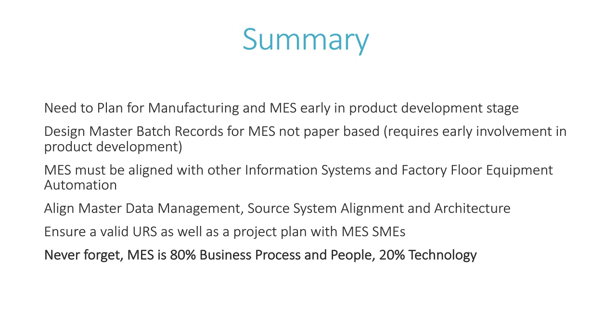So the batch record has to have the flexibility to be able to allow the operator to repeat that step multiple times. But when you create the batch record for the floor, you may not know how many times that is. So you need to have the flexibility for the operator or the management team to be able to make a decision on repeating certain steps in the batch record. So that's one of the examples of flexibility.